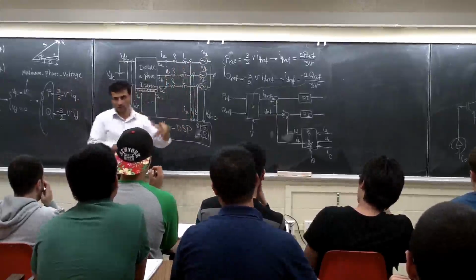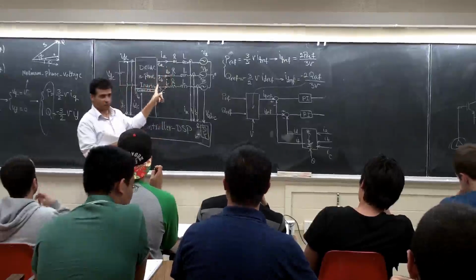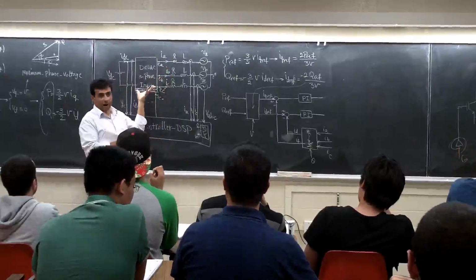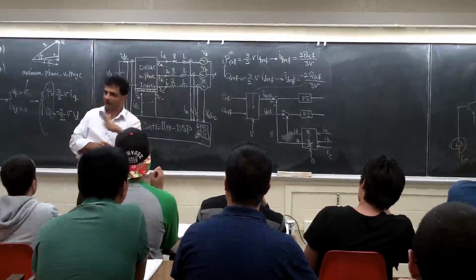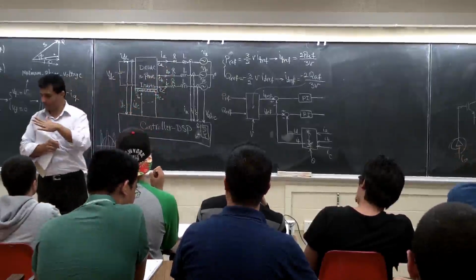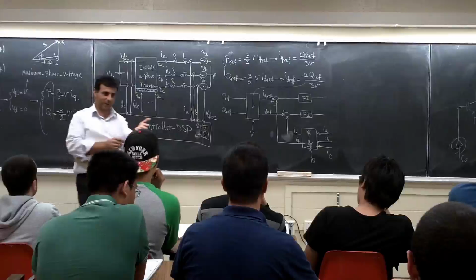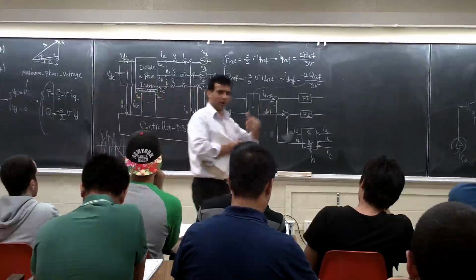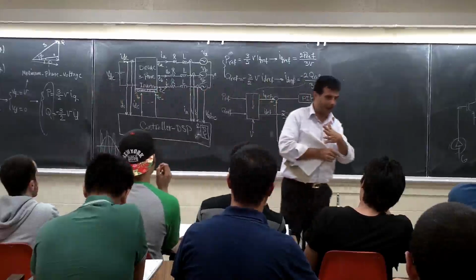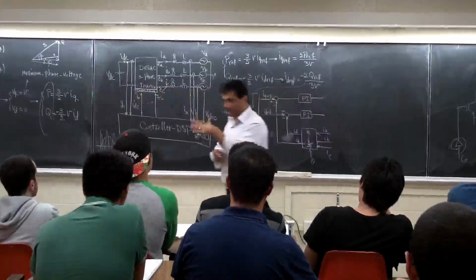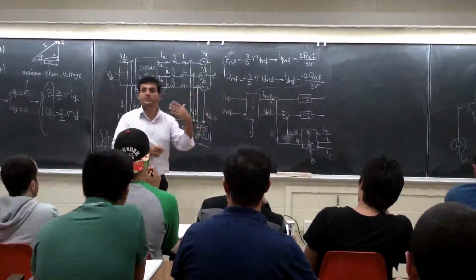The only thing that I can control is this voltage, right? With my inverter, I can change MA, I can shift it right, left. These are what I can do. You experienced that in phase one, as it goes 90 degrees ahead or 90 degrees back, so I can shift it back and forth. I can change my MA.